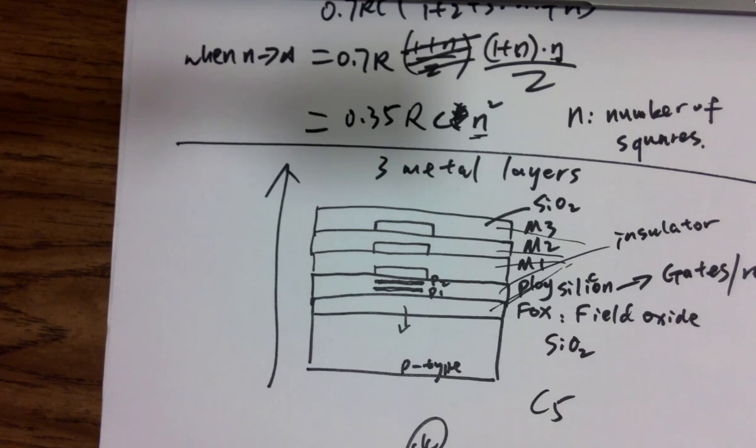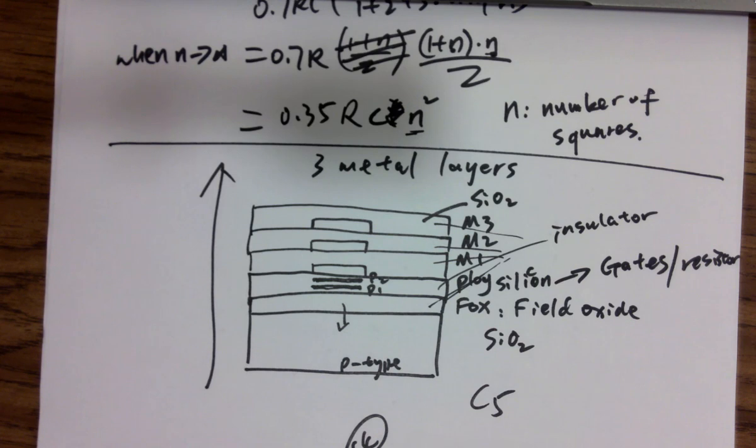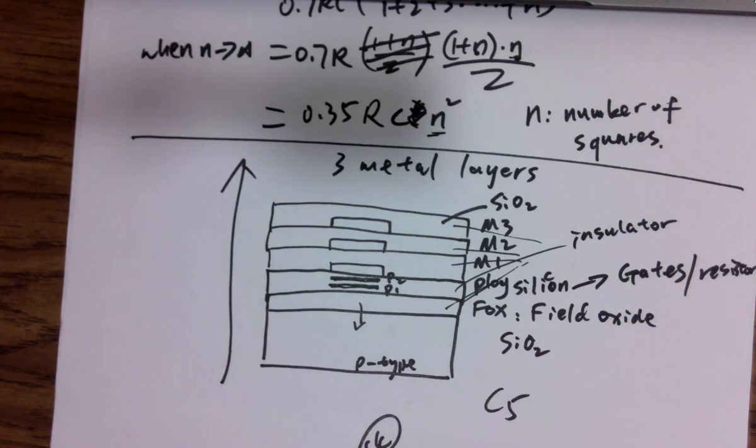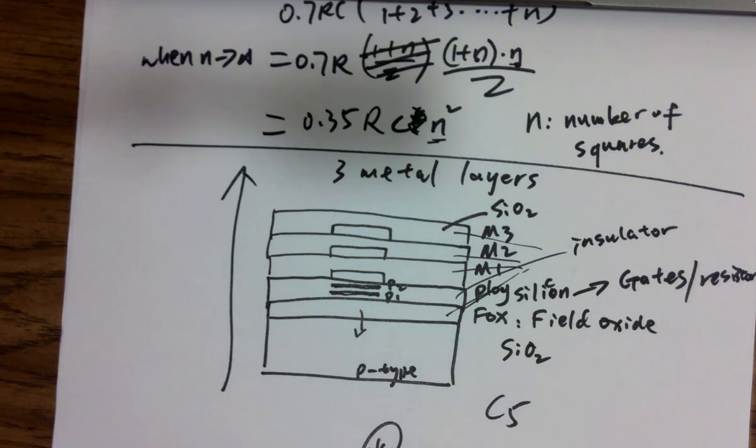But definitely, it's common sense that there will be more metal layers in more modern processes. I mean, TSMC 180 is not super modern, but still has a lot more layers than this. And the most popular ones, including 28 nanometer technology from TSMC, have even more. Almost double from 180, and going down to 5, there will be a lot more than this, you know. So you have more capabilities to route the traces on the top of the wafer. That's the goal, because it's highly integrated.